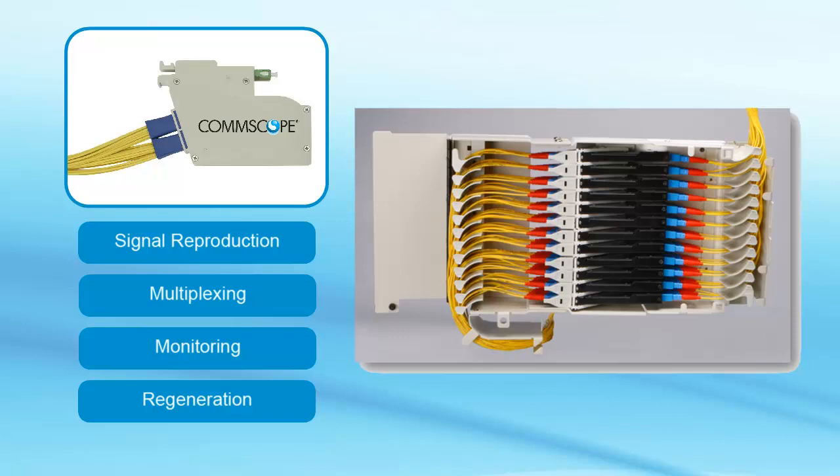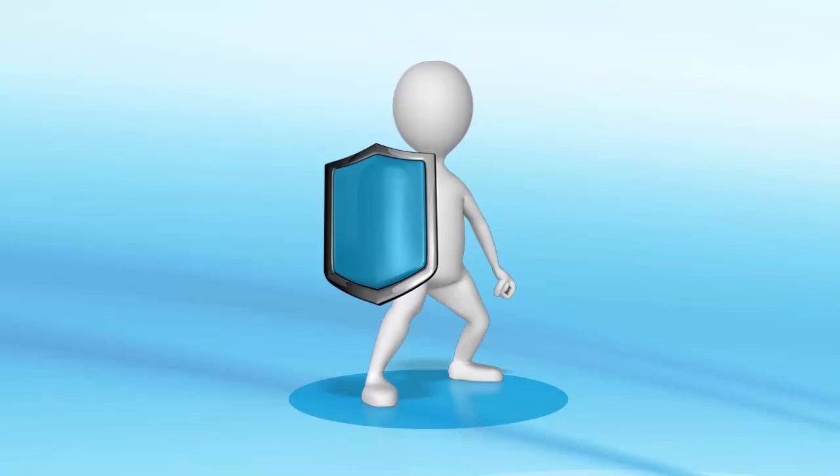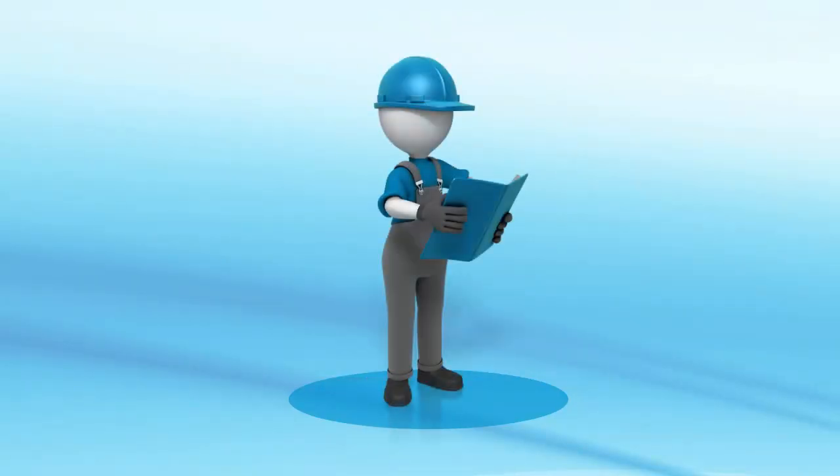If, however, the system is one in which the transmitters located at different points within the office are operating at the proper wavelengths for multiplexing, then locating the DWDM multiplexer and the demultiplexer passive components in the ODF may make sense. Whatever the optical components or the means by which they are incorporated into the fiber distribution system, they need to be properly protected. Bend radius protection and physical protection are the most important considerations for these devices. Following proper fiber cable management practices in incorporating these devices will reduce the cost of network installation and network reconfigurations.